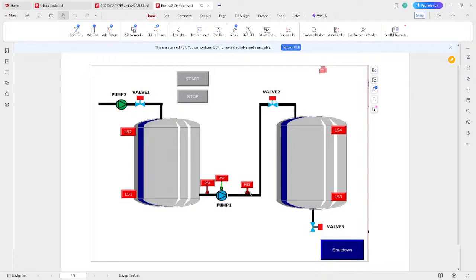I think I updated this because I drew this in SCADA. I updated this program later after the training, but I don't have it here. There's another level sensor here, which I added halfway. So once the tank is halfway filled, this pump one stops.